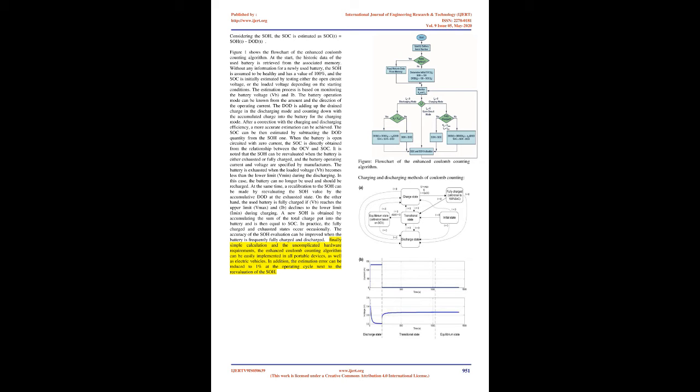The Coulomb counting method, also known as ampere-hour counting and current integration, is the most common technique for calculating the SOC. This method employs battery current readings mathematically integrated over the usage period to calculate SOC values, given by the equation where SOC(t0) is the initial SOC, C_rated is the rated capacity, I_B is the battery current, and I_loss is the current consumed by the loss reactions.